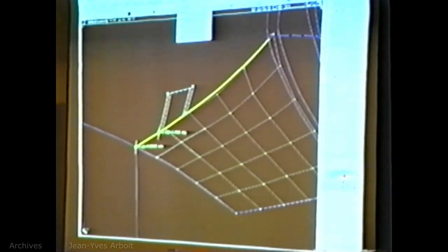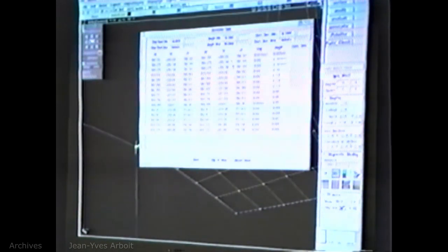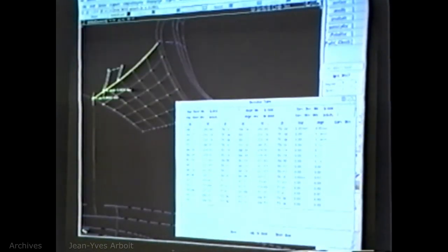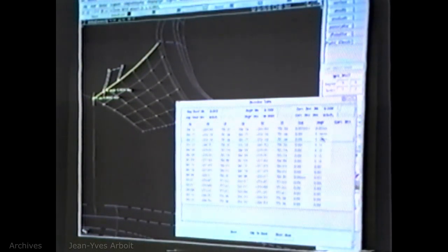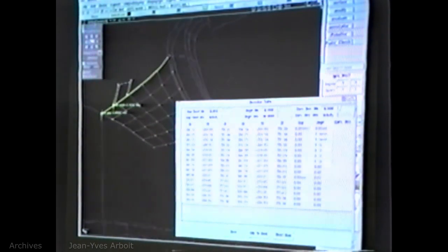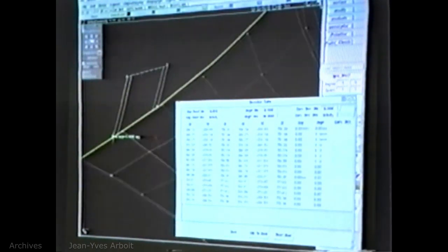and then if we take a look under Windows, there's a deviation table, and that deviation table gives you the ability to see specifically where the points are, in this case, deviation from tangency on the curve, or on the boundaries between two surfaces.